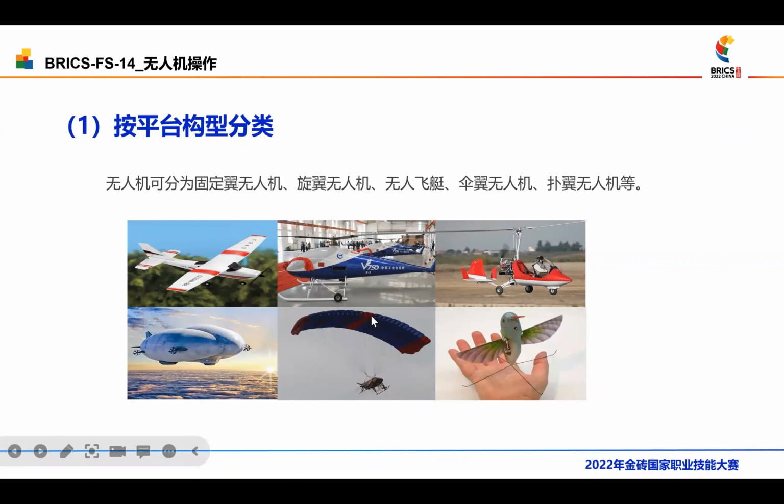The power parachute can glide, climb, and stay in the air. The most important is based on the Bernoulli theorem. The upper layer of the canopy is longer than the lower layer. When the air is divided into upper and lower parts from the front edge, the air flowing through the upper layer has a high velocity and low pressure, while the air flowing through the lower layer is slow and high pressure.